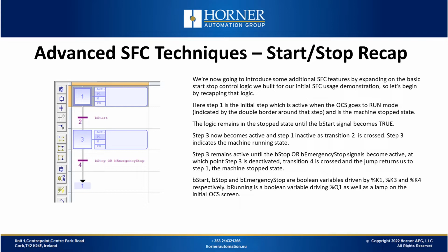A step becomes active when all the steps above it are also active and the connecting transition's associated logic condition is true. When a transition is passed, all steps above are deactivated at once, and after, all steps below are activated at once. So looking at our original start-stop application, which you can see on the left, here step 1